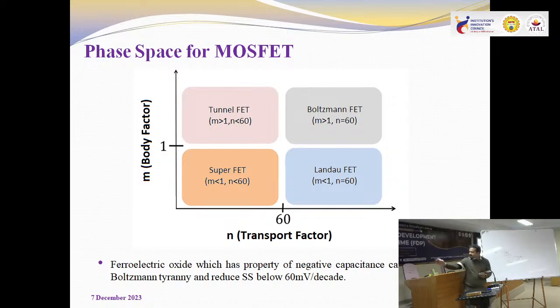Yes. So I have used this ferroelectric oxide, which has the property of negative capacitance, and that can overcome the Boltzmann tyranny and reduce the subthreshold swing below 60 millivolt per decade.